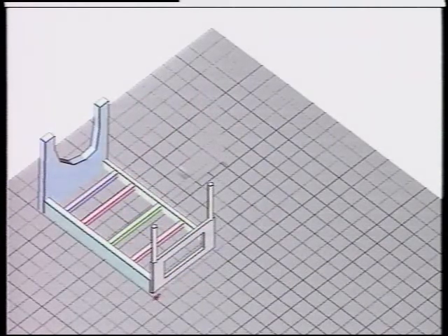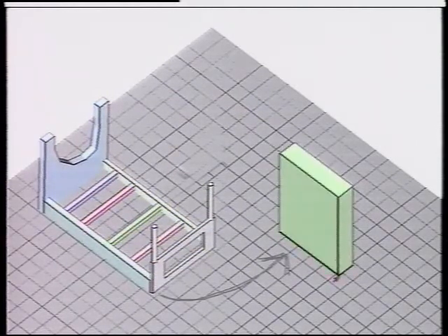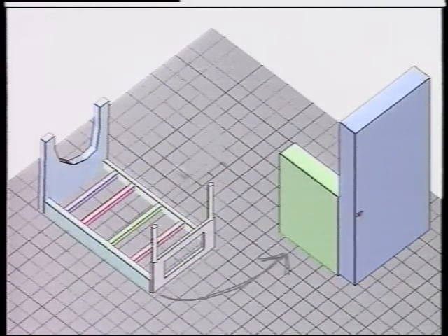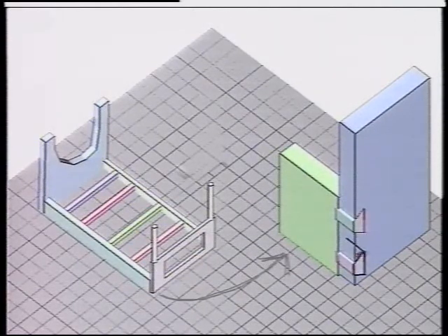Once the bed is done, we draw the detail of a dovetail joint, much as we might draw it on a piece of paper. Sketch supports schematic elements such as this arrow on the floor plane. Also, Sketch infers CSG subtraction operations from inflections of the drawings. Models can, of course, be interactively manipulated and are subject to default behaviors. Initially, objects are constrained to translate along the surface upon which they are created. However, we can easily sketch different constraints. Default colors are automatically chosen for new shapes to help differentiate them from existing objects.